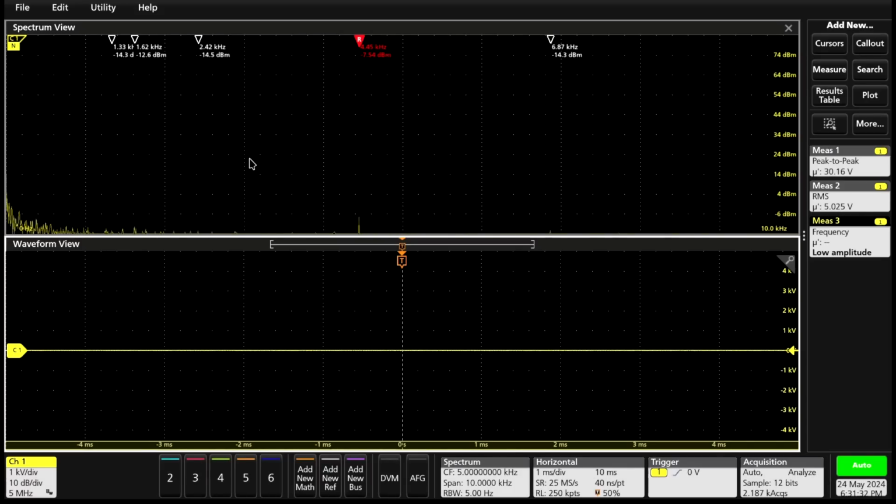This is a very simple test. We're only looking at the spectrum, and you can see a little bit of 1/f noise that's going to come from the active probe, as well as the instrument that we're using and the amplifier, which has no input right now, but this output is enabled. So let's go ahead and apply an input very carefully here.